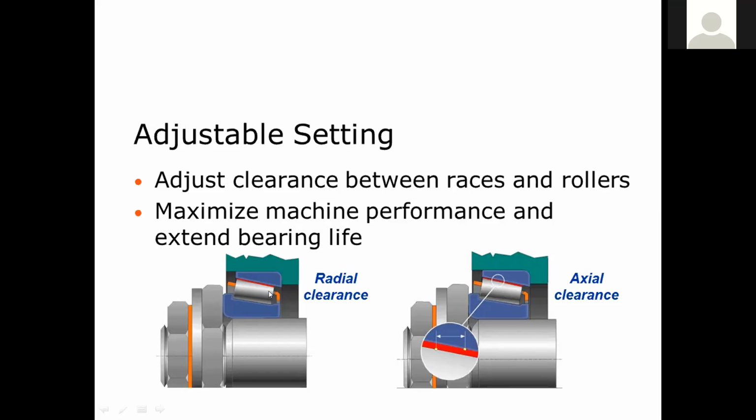In railways, we use condition monitoring methodology to predict the life of the bearings for the wheels. Absolutely. Condition monitoring could be even oil analysis, where you take out the used oil and analyze it, and you will find the metal particles. So you can decide if they have come from the shaft or housing. Correct. Or you understand the viscosity levels, ferroanalysis levels of the oil.